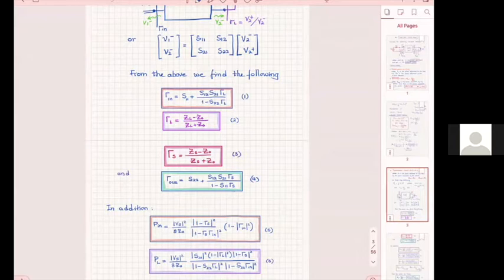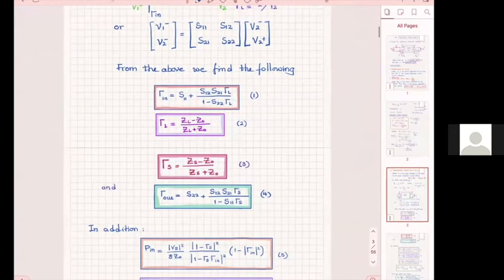So you have an amplifier design, and I will probably do it here, and then I will raise it. In an amplifier design, you will have 3 pieces, 3 components, if you want to call them this way. This is your transistor with whatever bias networks. This is your input matching network. This is your output matching network. All right, do we agree with this?